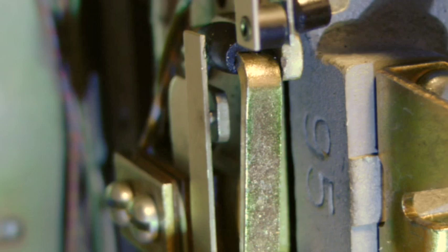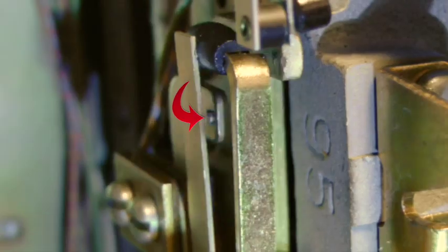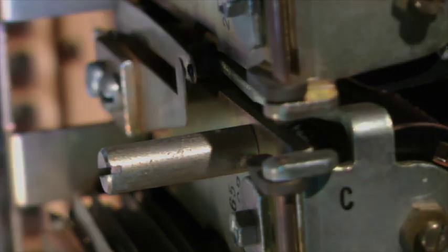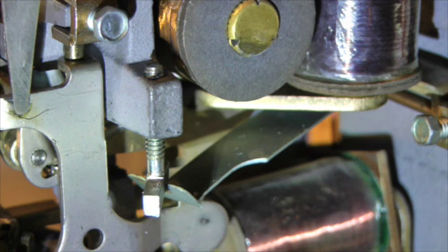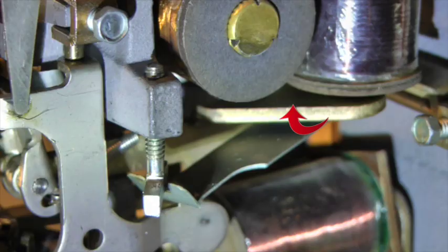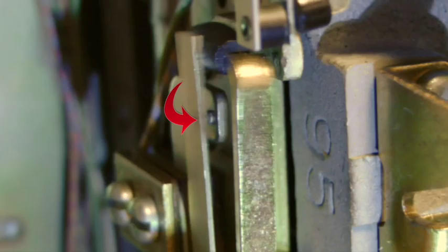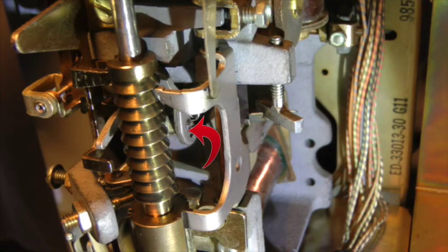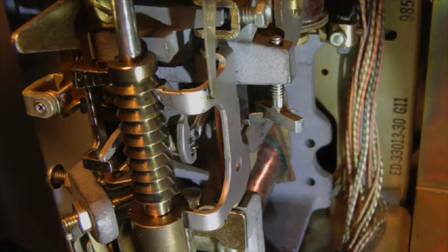When the vertical armature operates, its arm pushes upwards against the L-shaped vertical lever, which pivots and opens the contact springs of the vertical interrupter. This opens the operating path of the C relay, which releases. The release of the C relay de-energizes the vertical magnet, and so its armature releases. The vertical interrupter springs reclose. And the vertical pawl disengages from the vertical ratchet.